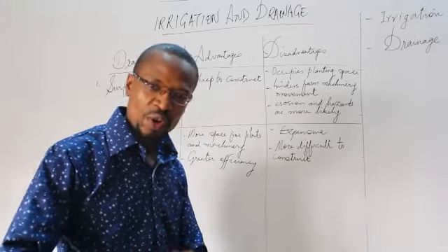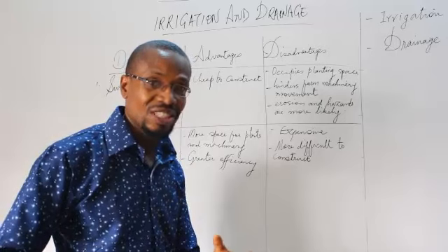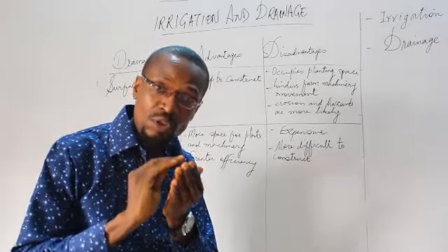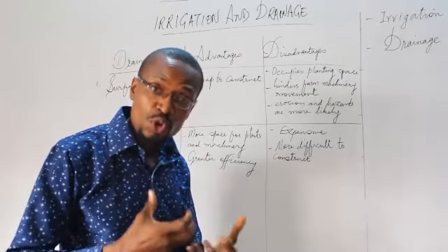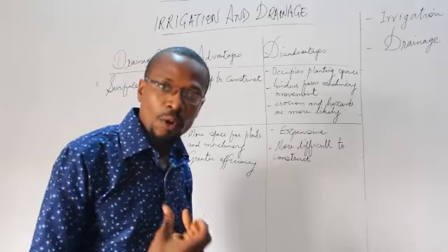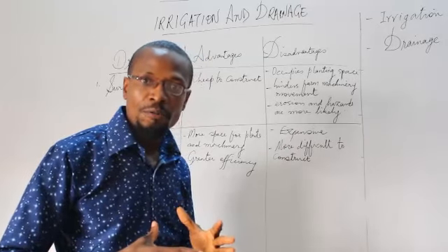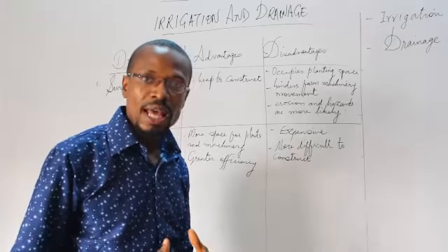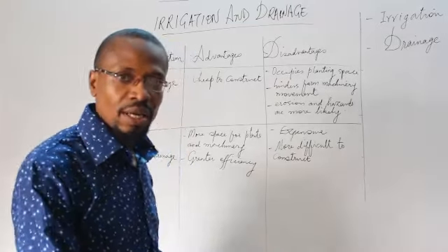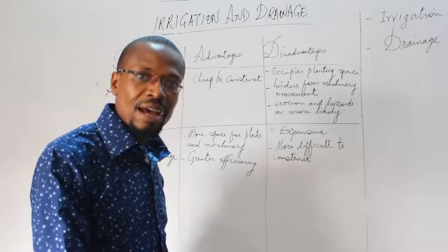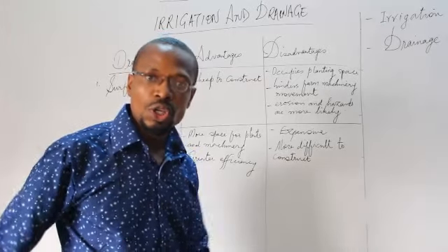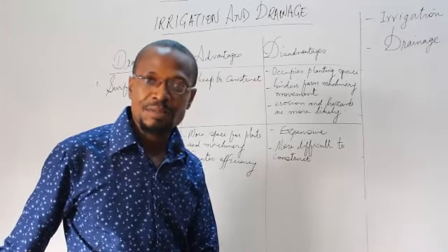Of course, you're not withdrawing the water completely such that it becomes sun-dried. No, you must leave some amount of water that will enable good farming activities, microbial activities, for nutrients, for the right amount of nutrients to be retained in the soil, and of course acidity, salinity, and all the other negative things that may affect the farmland by withdrawing this water also goes with the excess water that has been withdrawn.